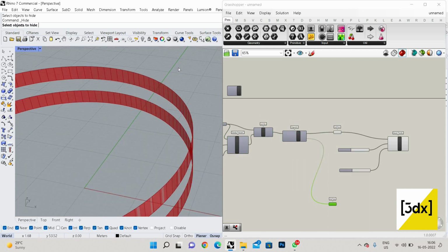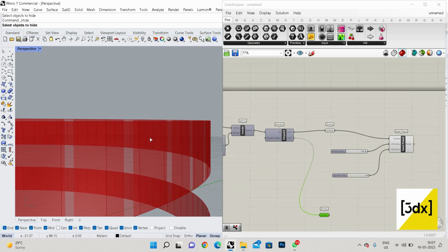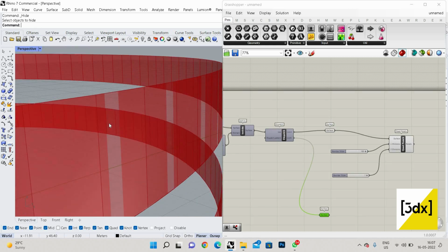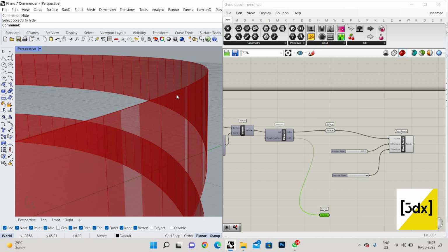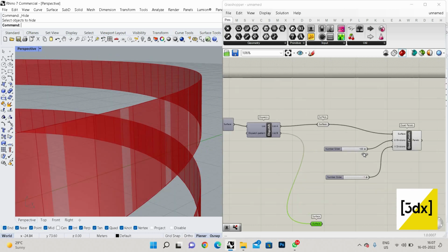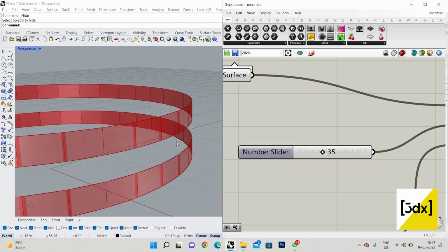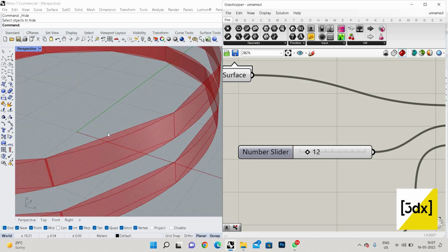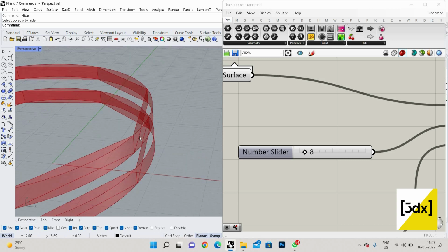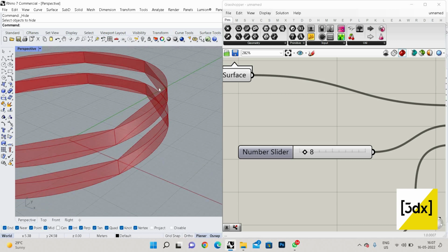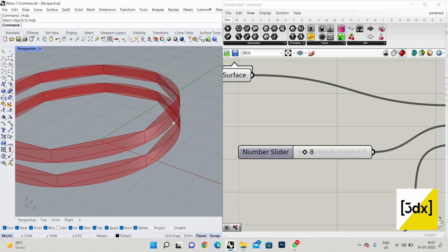I don't know whether you guys noticed in SketchUp, when you draw a circle and zoom in, it won't be a proper circle. It's kind of lines, like a polygon. Quadral. So the same, we're just making the quad panel. A quad panel literally makes the circle from n number of flat panels. If I reduce it, it becomes a hexagon. So from the curve, from the surface which we created, it gives you a quad mesh.